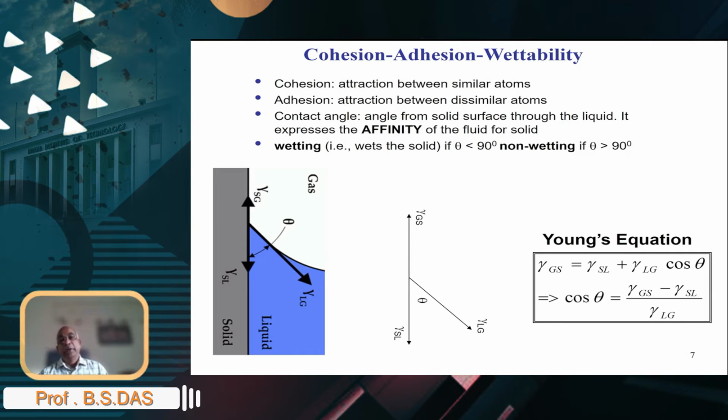And as we described earlier, at the interfaces there are unbalanced forces on the molecules. Therefore the adhesion, the attraction between dissimilar atoms, and the cohesion give rise to interfacial energies or interfacial tension for all three interfaces: solid-liquid, liquid-gas, and gas-solid.